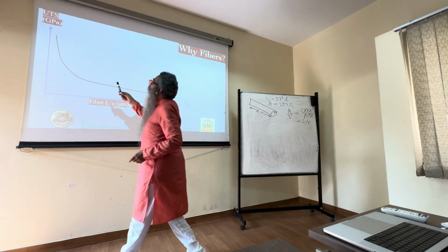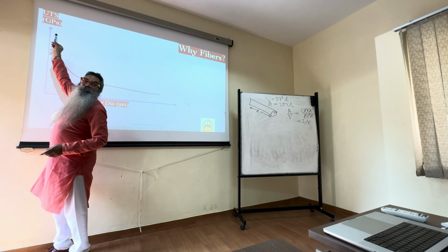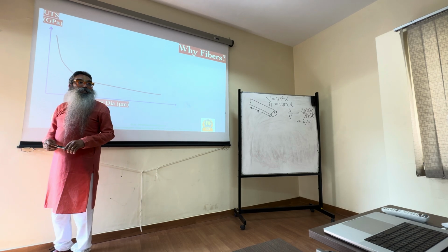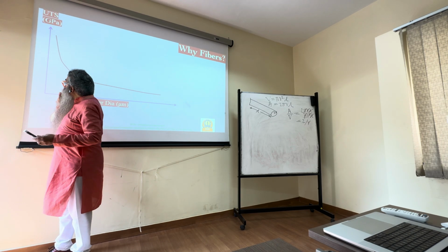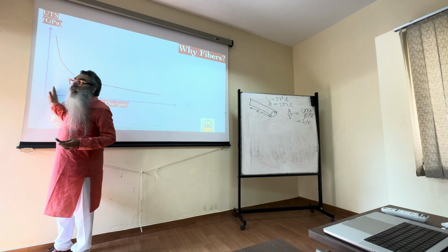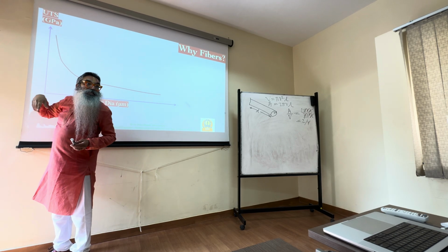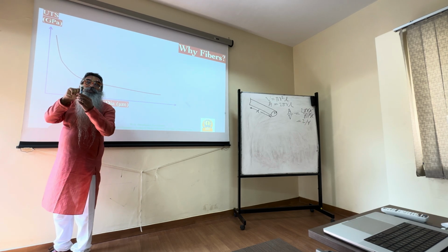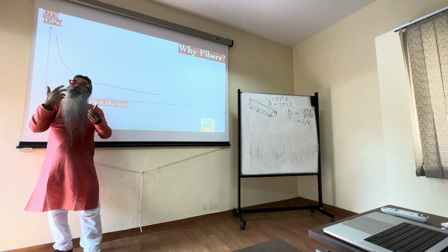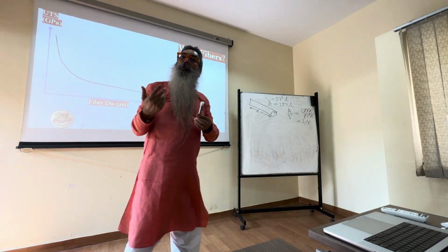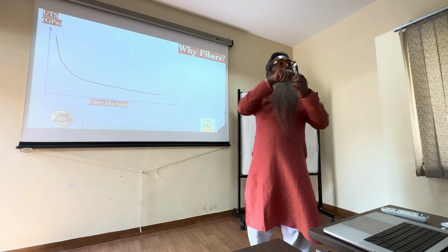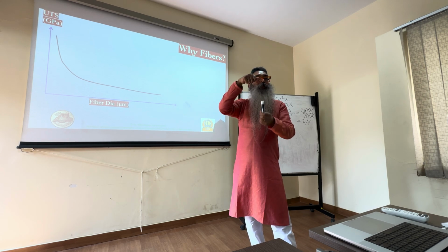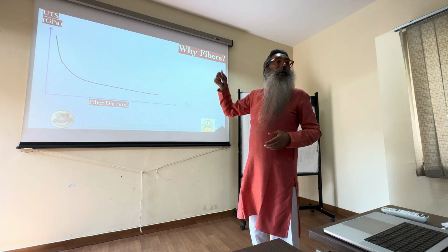So what happens over here? Again, as you said, it cannot increase forever. It has to stop at a particular point, which is dictated by the atomic size. First of all, the size is determined from that, and then the value of UTS at that point is determined by the interatomic strength. Whatever the bond strength is depends on the chemistry of that particular material. It could be a polymer fiber, then it's essentially the strength of the polymer chains, how much they have straightened out, how much you can still continue to pull on them. So those things determine it.